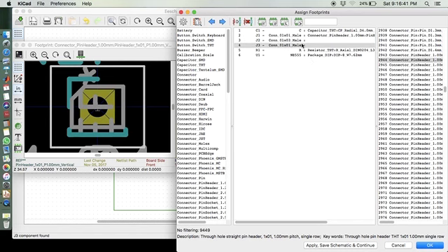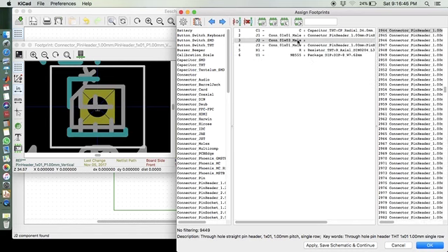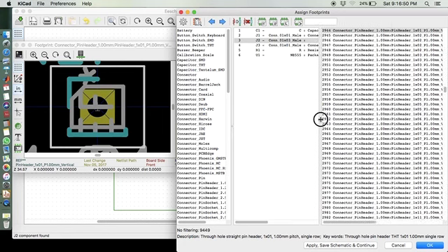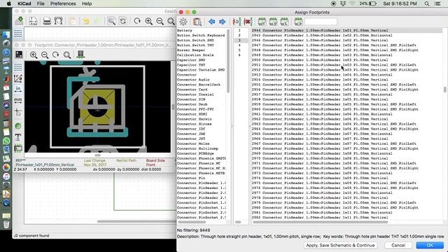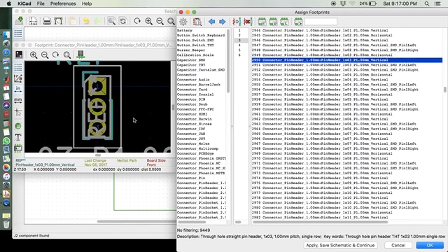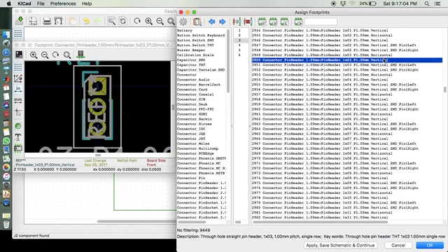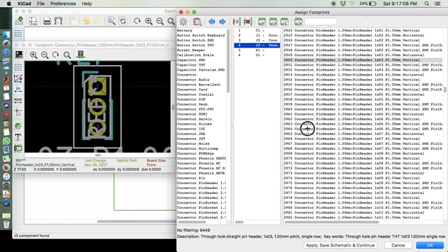And this is also a single pin connector, so you'll choose the same thing. And this is actually a 3-pin connector. See, look at the 3. So where is it? These are single pin connectors, so we need 3-pin. These are horizontal connectors, we need a 3-pin vertical connector like this. Okay, so 3-pin vertical connector. Double clicking on this will assign that connector.